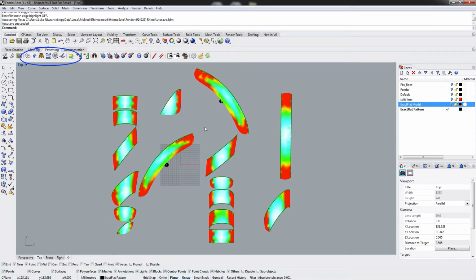So our pre-flatteners, they are very quick flatteners that get you unoptimized flat patterns that often have quite a bit of strain. And our second flattener is our optimizer. That's the spring icon here. This is a much more accurate flattener, and it actually relaxes and relieves all the strain from the pattern piece to give you a production pattern.